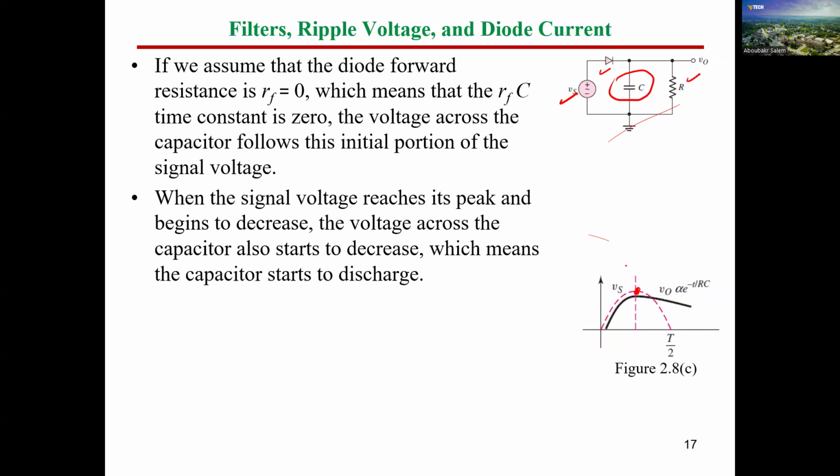But the diode, we used to have the diode turned off in the half-wave rectifier at this instant. But this will not happen now because you still have a supply, and the capacitor is going to supply our load because the capacitor will discharge in this resistance. So once the voltage here starts decreasing and reaches the capacitor volt, this diode will be turned off. And the load current will continue operating, depending on the current coming from the capacitance.